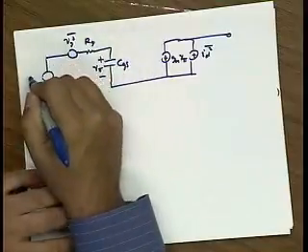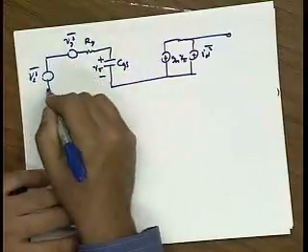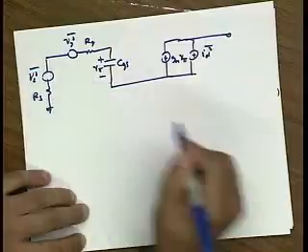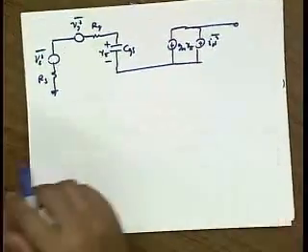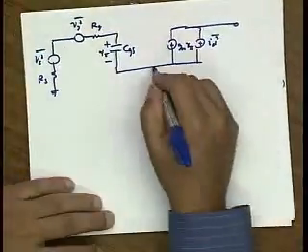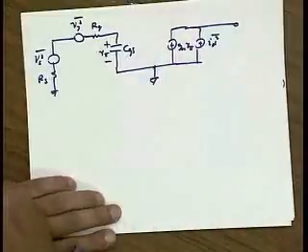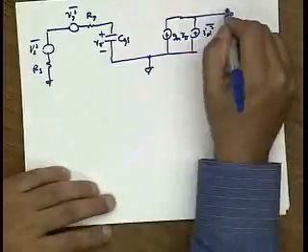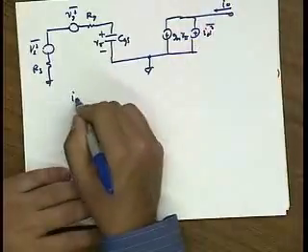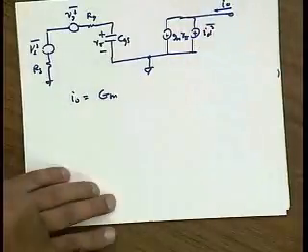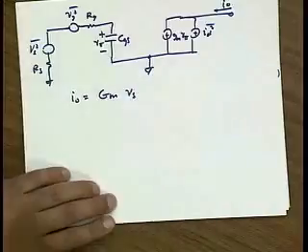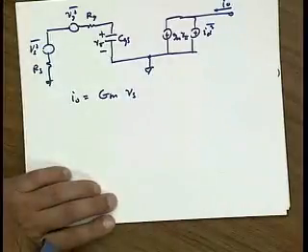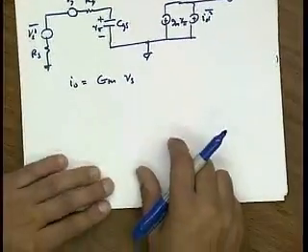And then finally we have our noise source and our source resistance. Okay? And I'd like to just recalculate the noise figure of this, making the observation that the output current, let's say I out, is some capital GM of the source voltage. Okay? So I want to calculate that capital GM.